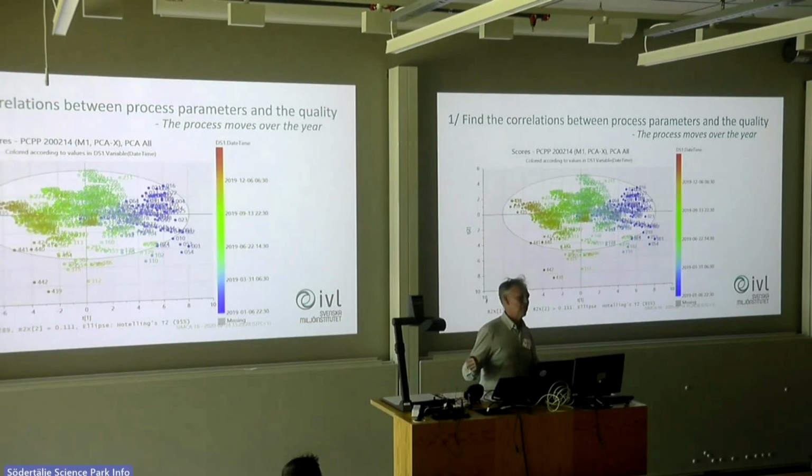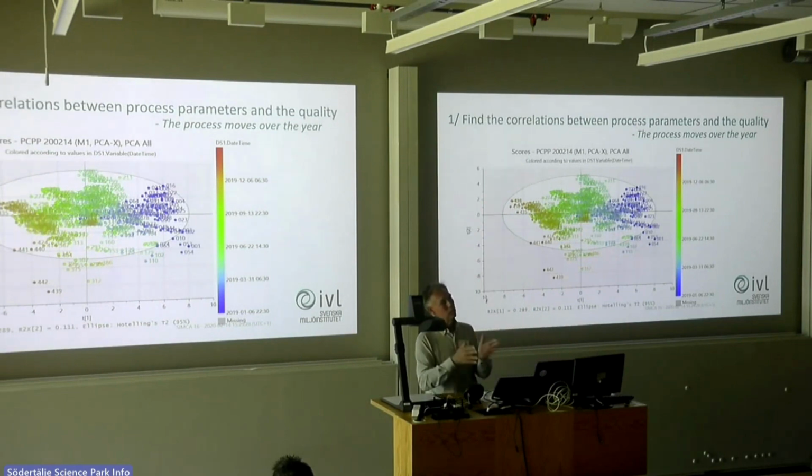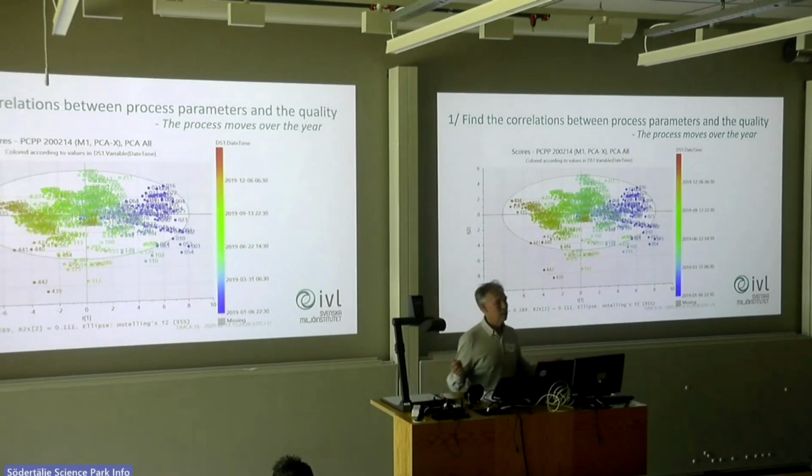You have several ways of analyzing the quality. Here, for example, I think they have been analyzing the thickness, the weight of the crystal, the phosphate layer, but also measuring the crystal size. We have been working in Scania, where we go not just analyzing the phosphate layer, but also analyzing the paint, how it affected the final result of the paint.